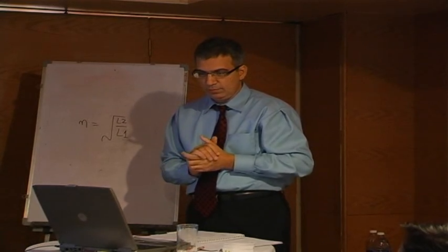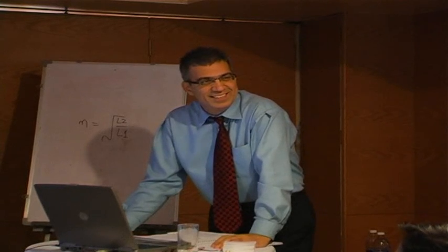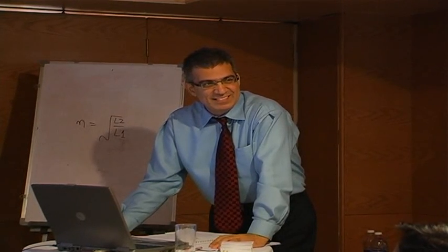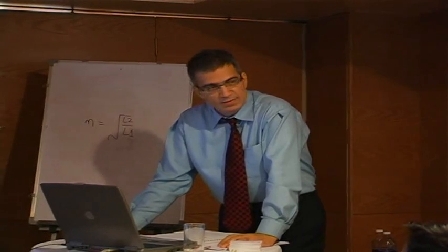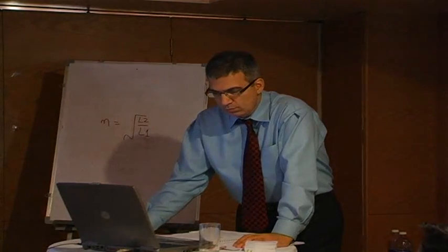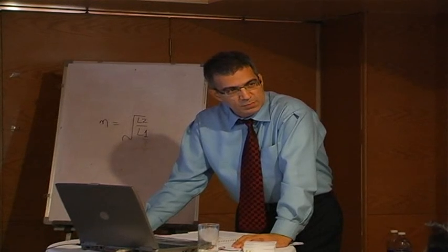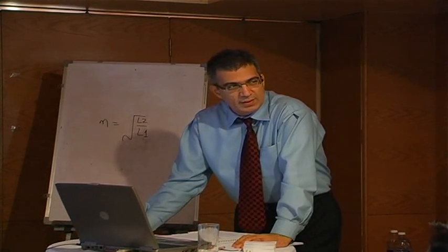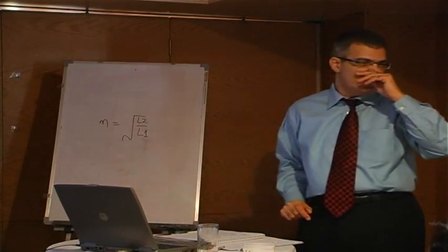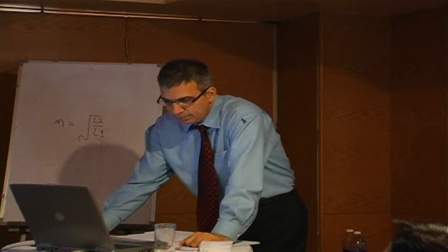But why is there a peak at 10 kilohertz? That's an artifact. You have to just take one period. Right now it's taking the entire data from the transient, from the initial start. If you select it manually on the steady state, you will get only the steady-state content. That's a good point.